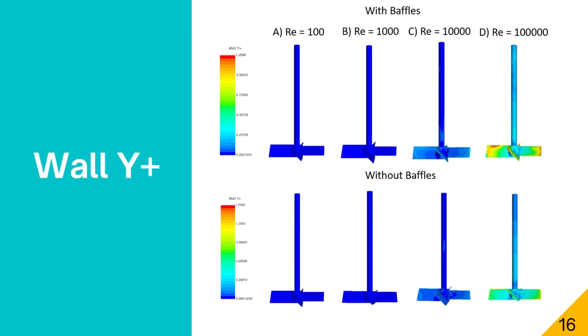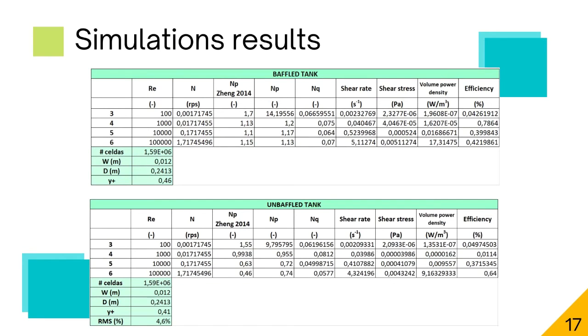It is recommended to use lower values of Reynolds so the value of the Y+ does not affect the calculations of wall shear stress. Additionally, it is desired that values around 1 are used so wall functions are more precise. As shown in the table, the Kappa Omega model gave different performances for the baffle and non-baffle system. For the case of the baffle tank, a good agreement is observable at large Reynolds, while an overestimation was encountered at low Reynolds where early turbulent conditions are present.